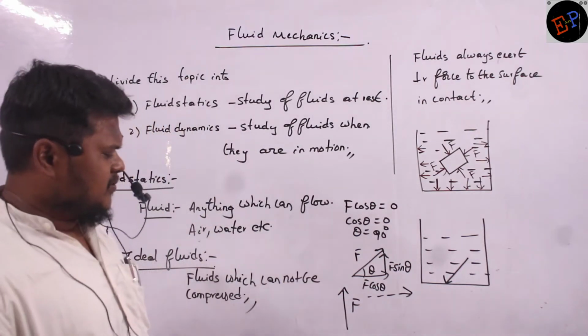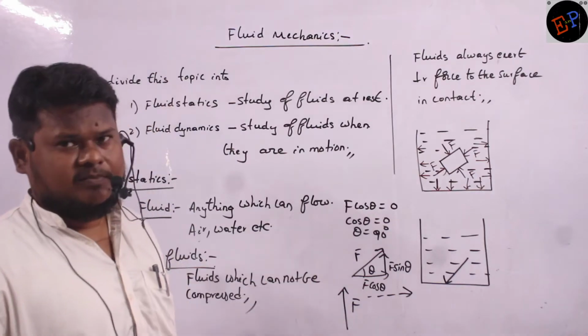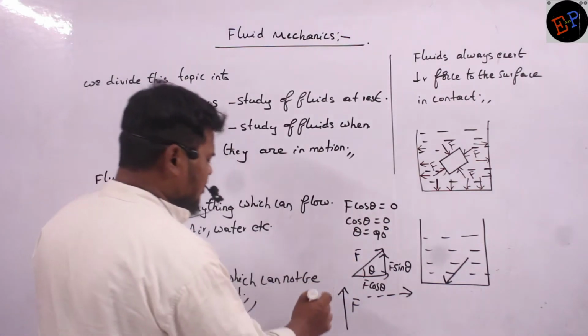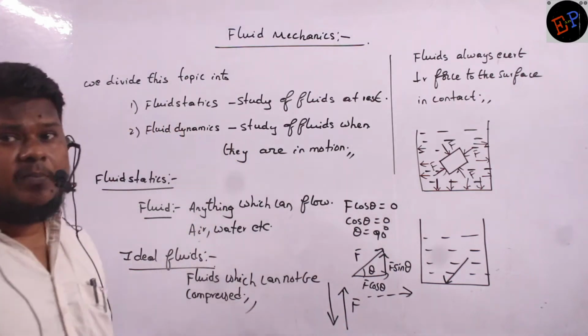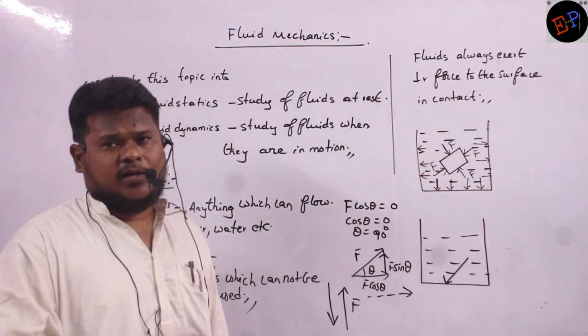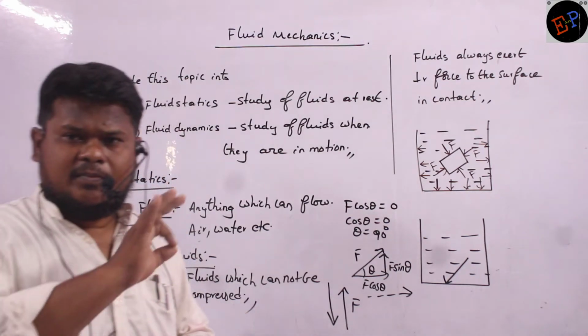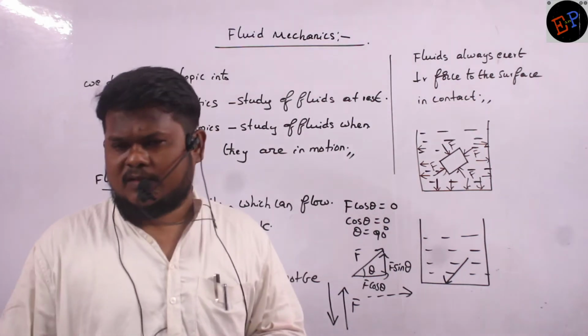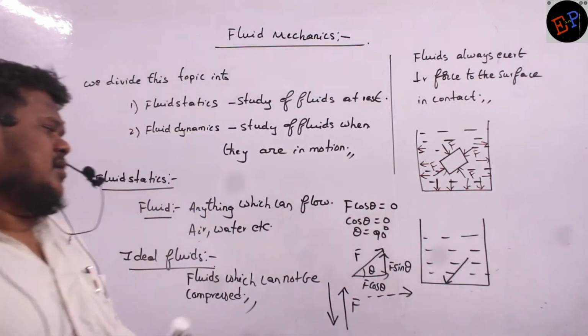Okay, and if this force applied by the base of the container on the water molecules is in this direction, it also means that water is applying force exactly in a downwards direction, or perpendicular to the surface in contact. So therefore we say that fluids always exert perpendicular force to the surface in contact. So this is one point which you should be very careful about.